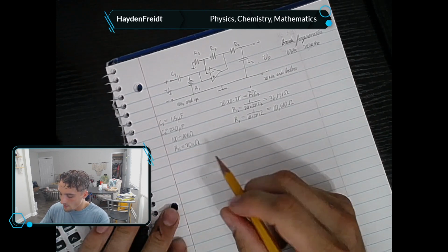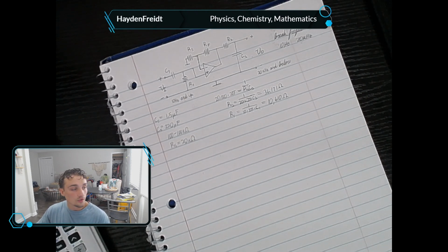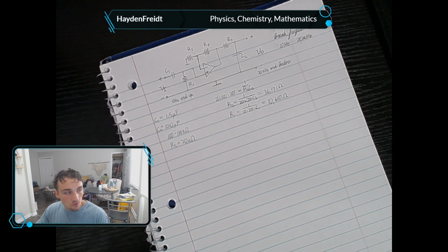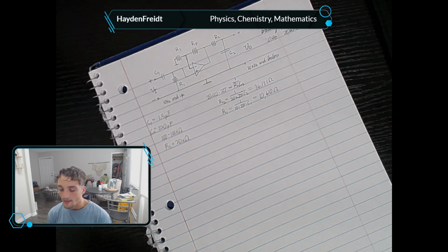So we've determined that. We know that RS is 20 kilo ohms, and now we need the value of RF. This also wants mid-band frequencies, such as signals around 1 kilohertz, to be amplified by about a factor of 2. Let's write down what we know.